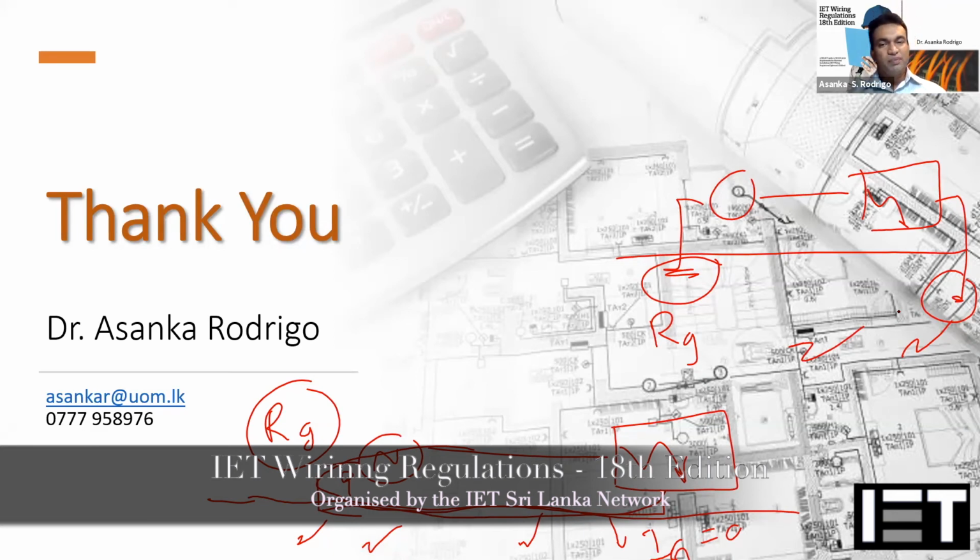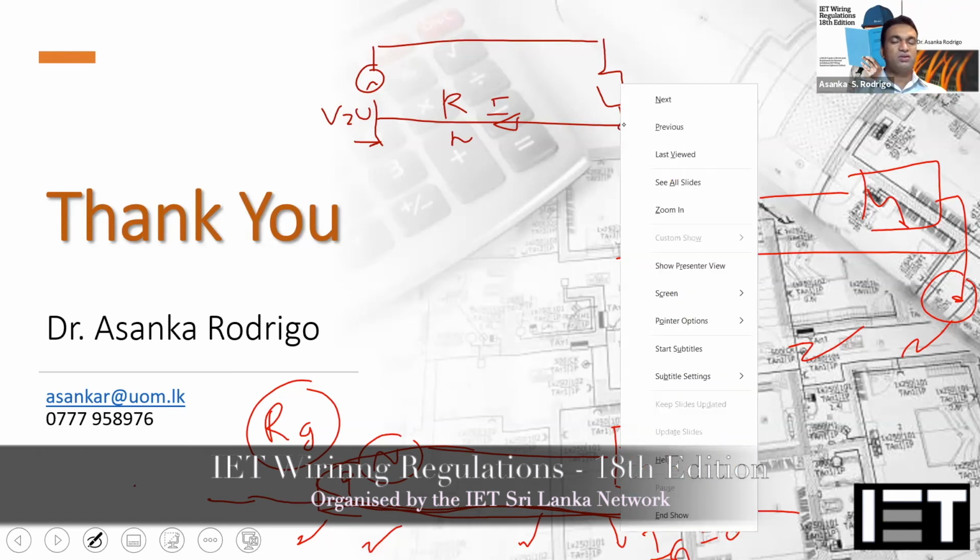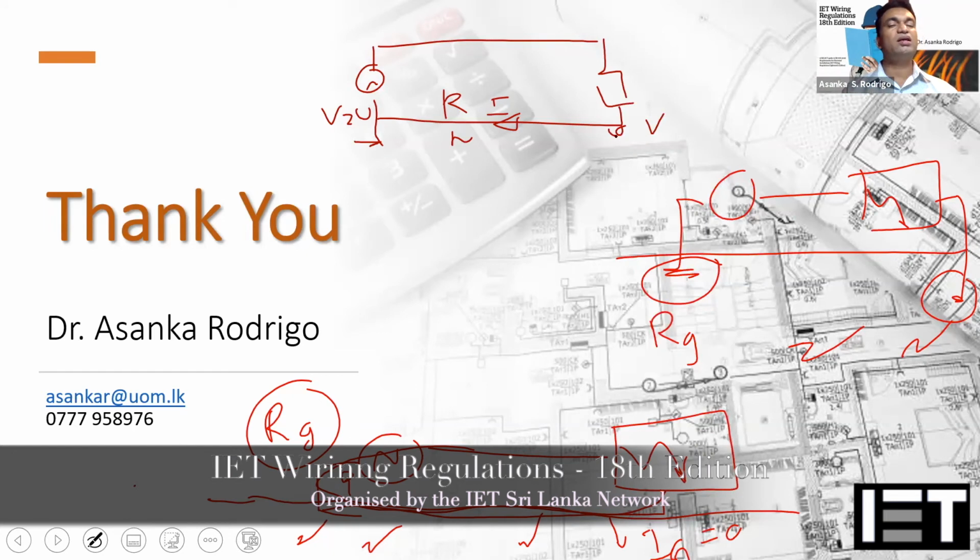As I said, one of the problems with the TT system is that you have a separate neutral earth and then you have a neutral conductor. Especially in an unbalanced situation, there will be a large current flowing through the neutral conductor. Even though you are maintaining the voltage at 0 here, due to the current flow and the resistance of the neutral conductor, there will be a large voltage drop or voltage increase at the end equipment. This is the situation you will face in the TT system.